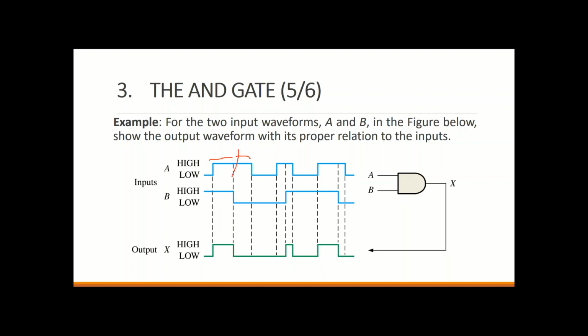So you need to place the timing diagram based on whichever edge moves from 0 to 1 or from 1 to 0. Here we have the movement from 1 to 0, so you place the timing diagram accordingly. Again, you do the same. Since you have 0 here, you don't have to care. Or low level. Again, the same low level here.